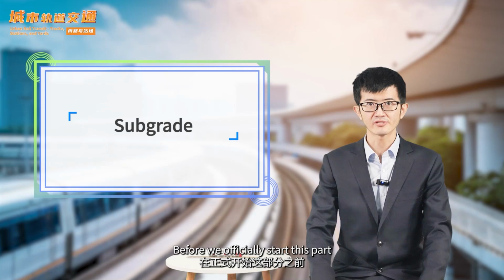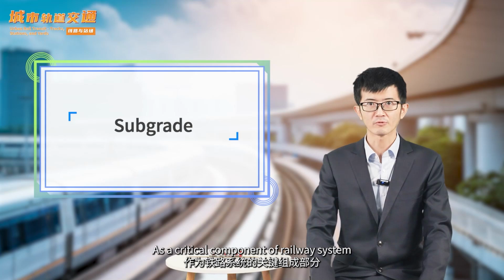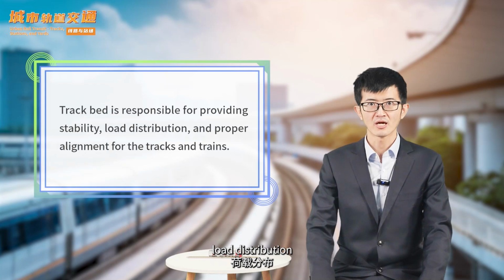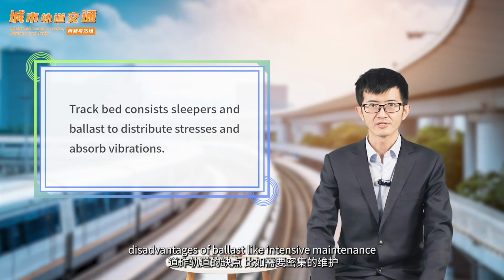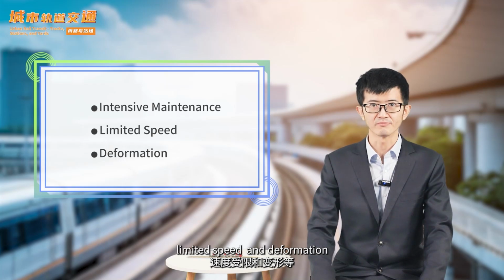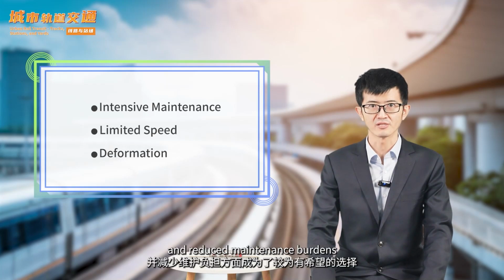Before we officially start this part, let's take a brief review about the track bed. As a critical component of the railway system, track bed is responsible for providing stability, load distribution, and proper alignment for the tracks and trains. Generally, track bed consists of sleepers and ballast to distribute stresses and absorb vibrations. However, disadvantages of ballast like intensive maintenance, limited speed, and deformation make ballasted track less attractive. Non-ballasted track, therefore, offers a promising alternative for railway engineers seeking improved performance and reduced maintenance burdens.